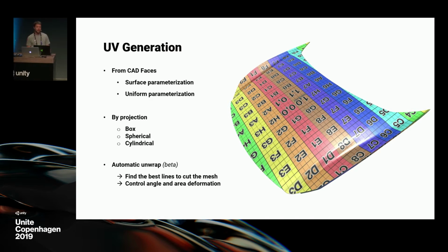There are several ways in PiXYZ to generate UVs. First, the UVs can be generated during the tessellation process by using the two-dimensional parametrization of the surfaces. We can also uniformize this parametrization to make it consistent in 3 dimensions. Another fast way to generate UVs suitable for baking is by projection. This method induces more seams and deformation, but is fast to execute and works quite easily.